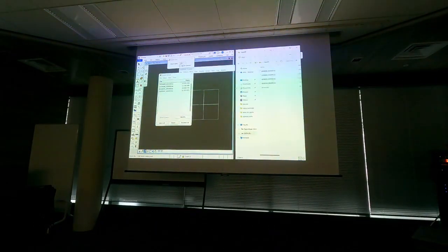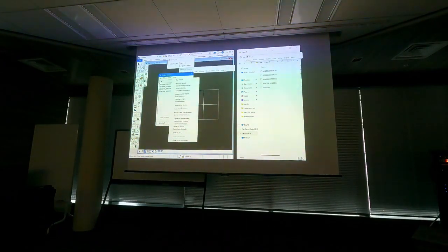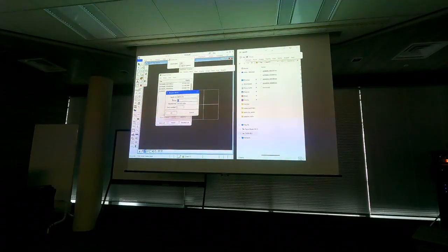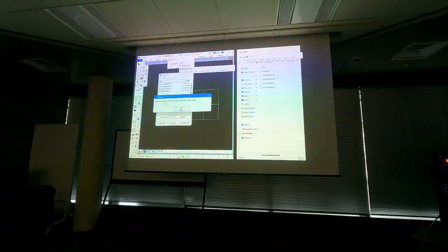And that is the files. Now in the project window I can say rename blocks. I want to use prefix Kerava and perhaps current order and say that numbering should start from 1001. That changes the naming in the project and it renames the LAS files. It tells me renamed 4 blocks and 4 block files. Remember to save project. So now it's important to save the project.